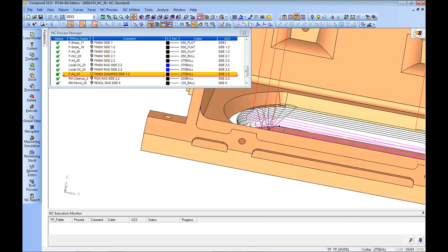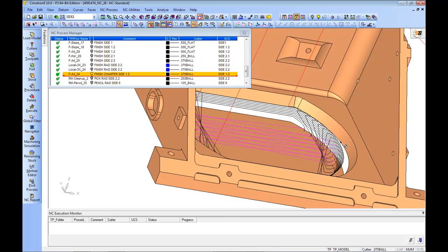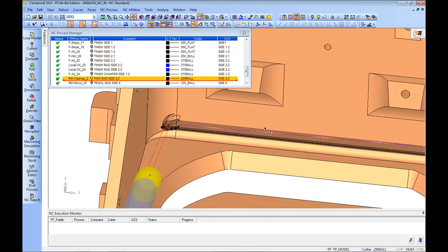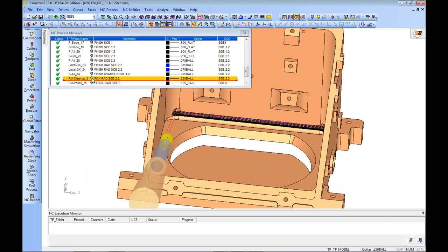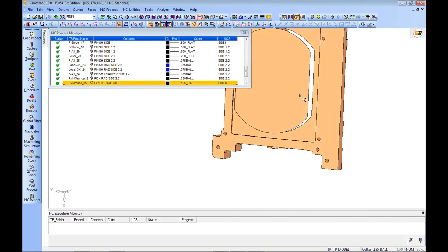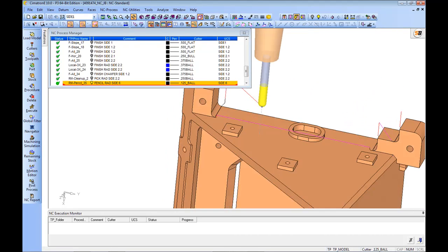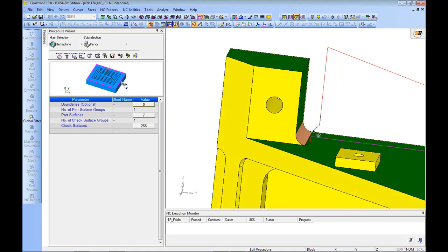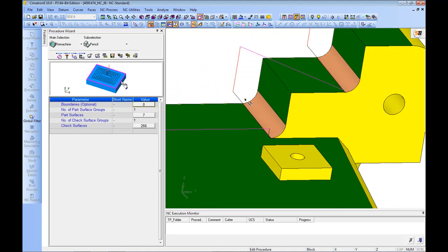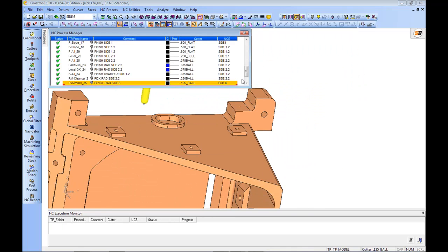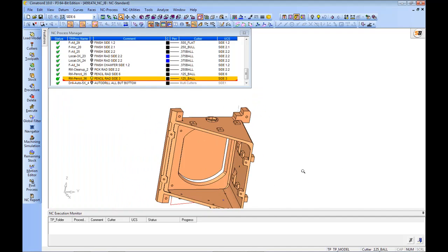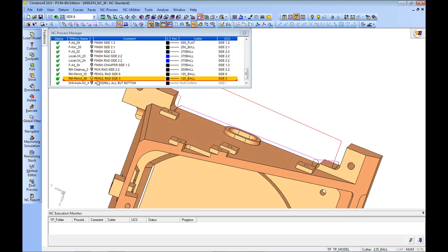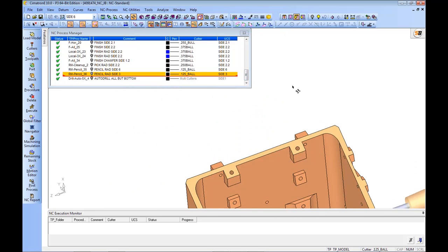Then here's a doing that chamfered edge all the way down. Remachine with a 1/4 inch ball. Then this one is a pencil cut where we're picking this edge and this edge and giving us a single pass in between them. Another pencil, get those radiuses established. And then my favorite, auto drill.